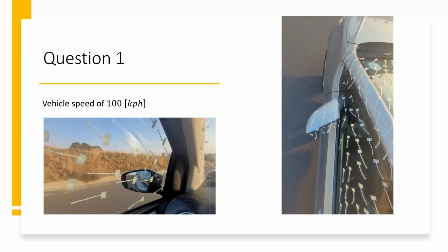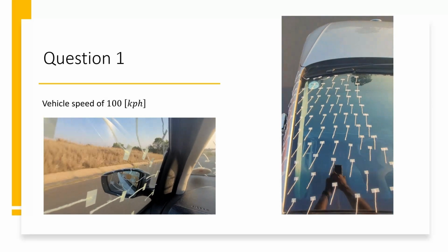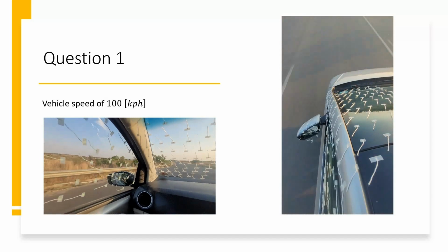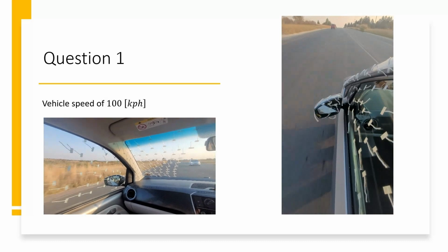The turbulent flow around the side view mirror also creates a noticeable amount of wind noise that reaches the inside of the cabin. It also affects an area of flow on the door and side panels of the vehicle behind it. The flow between the side view mirror and the body of the vehicle is highly turbulent.